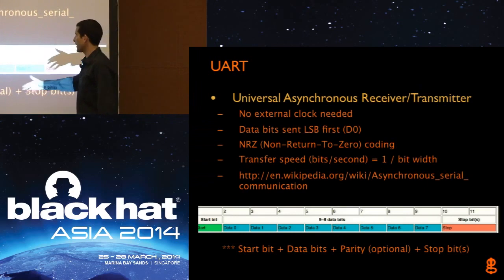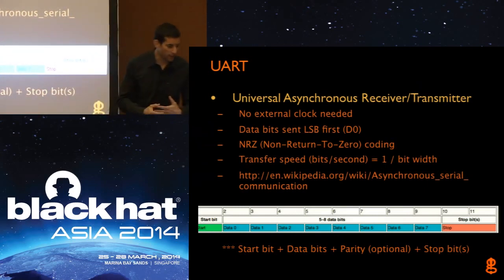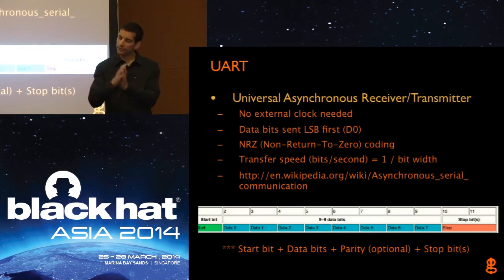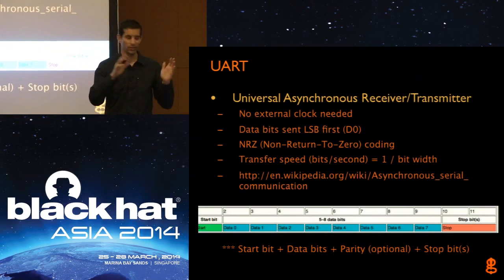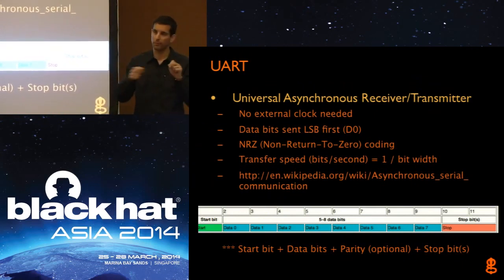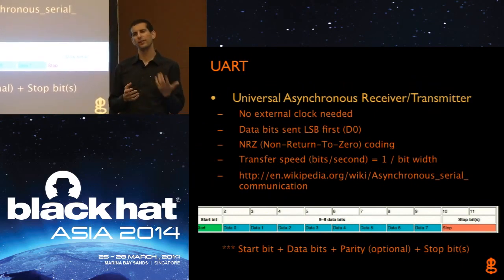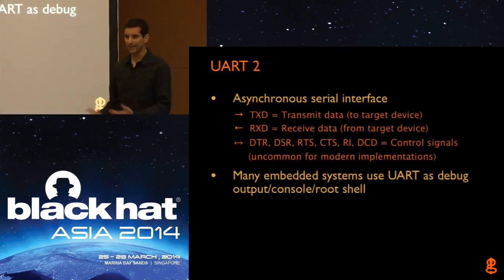And here's sort of a spec. You have a start bit, 5 to 8 data bits, and then a stop bit. And looking at UART data, the more you look at it, the more obvious that it's asynchronous serial versus some other signal. So if you're probing a board, you might be able to take a guess and go, oh, I think that's a UART. But in most cases, being able to automatically detect it will be easier.